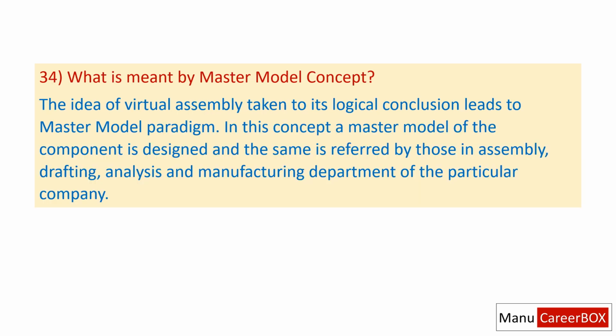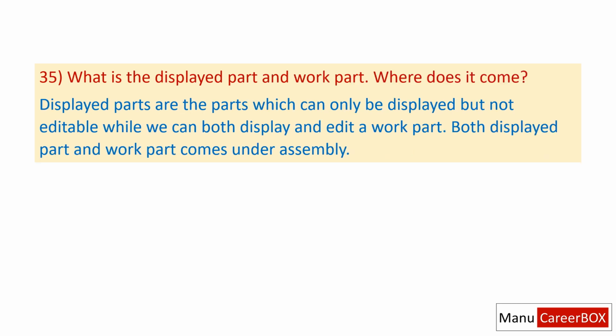34. What is meant by master model concept? The idea of virtual assembly taken to its logical conclusion leads to master model paradigm. In this concept, a master model of the component is designed and the same is referred by those in assembly, drafting, analysis and manufacturing department of the particular company.